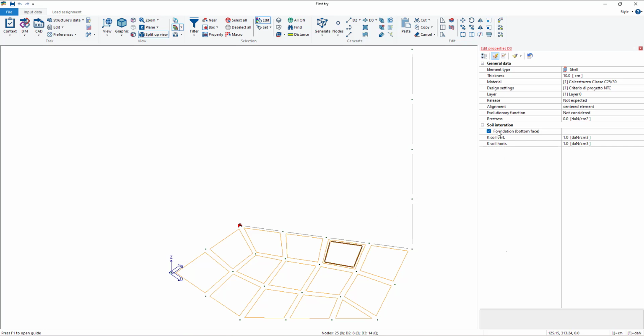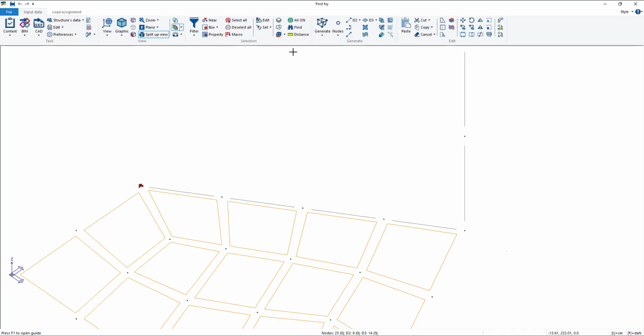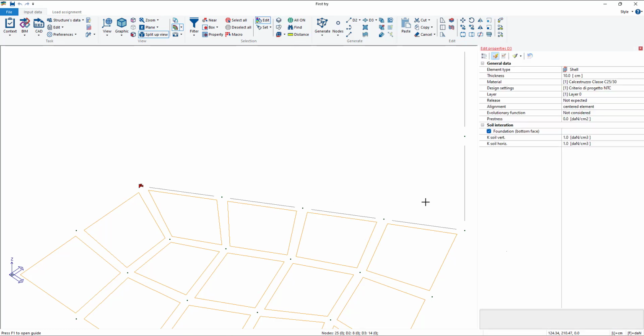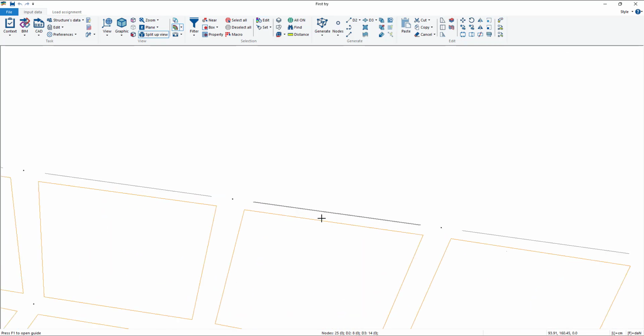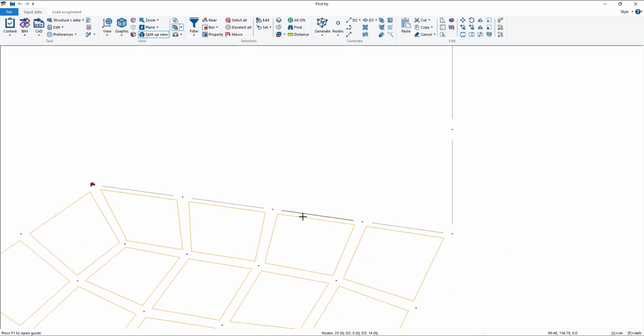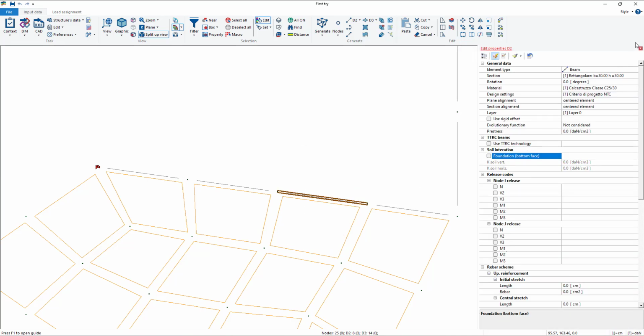And when you have an element become a foundation, if you close it, you should see it a little thicker. You can use that, of course, on D3 and on D2, not on nodes. On nodes you have to use external boundaries. So here, if I use foundation, you see that the element is thicker. So when an element is defined as a foundation, it appears thicker, so you can immediately see which they are. Okay, so let's take this out.